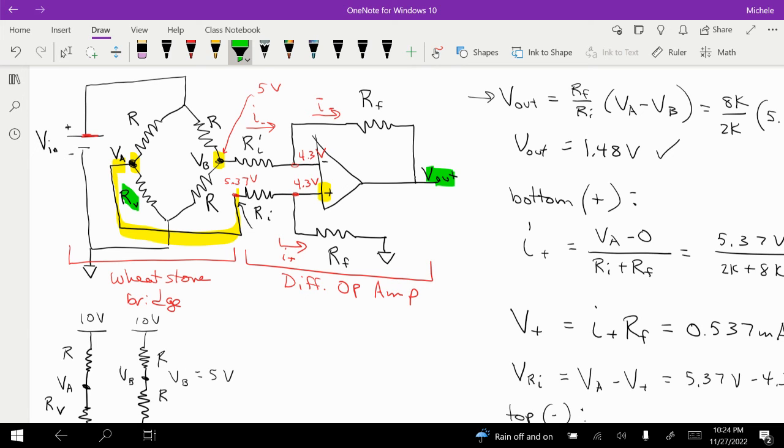And so what you can do with a circuit like this is feed this into another circuit that controls something about the environment that would change the value of your RV. If I were trying to control the temperature, I could use this V out as input to something that heats something up, so that I could increase the temperature.